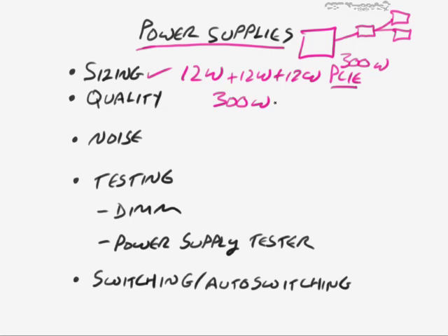And I'll say, okay, I'll go to the electronics store and I'll buy the bare minimum cheapest 300 watt power supply that I can get. But that would be wrong because normally you don't want to max this out to the absolute total maximum that it's ever going to need. Generally speaking, what you'll do is you'll multiply the amount of watts that you think you need by 0.6, because you don't want to use any more than 60% of the power.